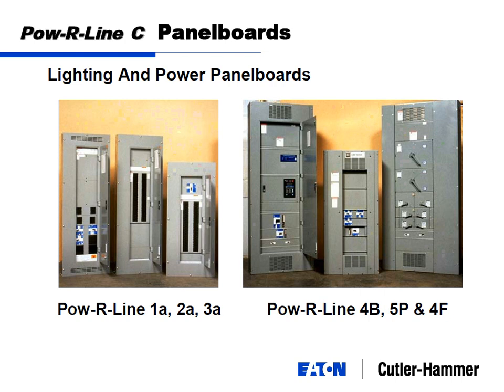That main switchboard will then distribute to more than likely a second level of what they call power panel boards. Maybe this is a 600 amp panel board that feeds 4 other panel boards. So this could be a case where it's a 600 amp panel board and it's got 4 100 amp breakers that feed 4 more panel boards.